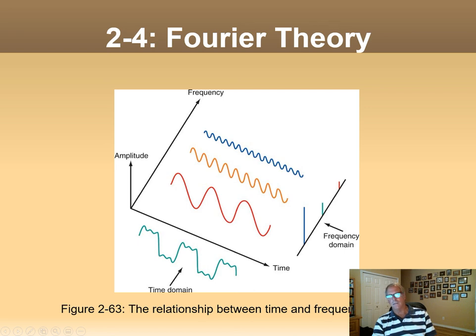So here's a little diagram. This is showing the time domain. If you notice, there's a lot of ripples on this square wave. This looks like it's becoming a sine wave. This is a bandwidth limited square wave because some of the higher order harmonics have been removed, so it's starting to morph into a sine wave. And this shows the fundamental and then the harmonics. The frequency domain shows these spikes here. This is, again, what we'll see on our spectrum analyzer.